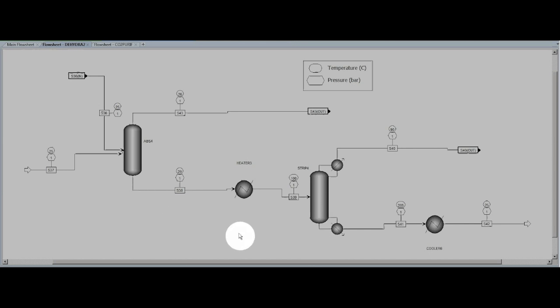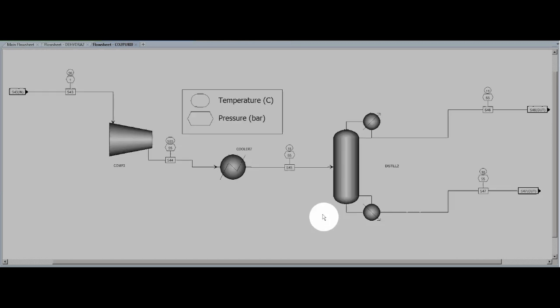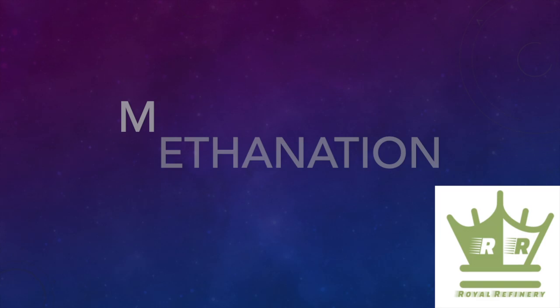CO2 purification. To purify carbon dioxide, TEG dehydration is used to bring the water content down to 20 parts per million, as this is required for food-grade CO2. This involved the use of a stripper and the recycling of the water. Then, through the use of a distillation column which operates at 60 bar, the carbon dioxide is further purified. The bottom stream, which consists of food-grade carbon dioxide, flows at 20 degrees Celsius and 60 bar. A modified Peng-Robinson model was chosen as it accurately accounts for the interaction between polar and non-polar mixtures. A shortcut distillation column was used for this step as it provides a good separation.